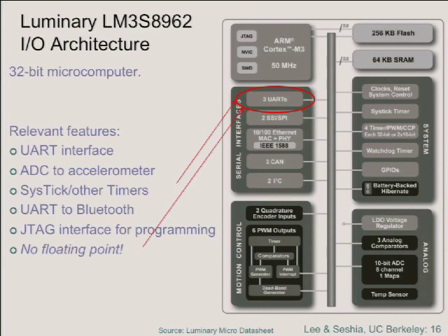By the way, the trends in interfaces are very strongly towards serial interfaces rather than parallel interfaces. It used to be that, for example, in the old IBM PCs, you had a serial interface and a parallel interface. A parallel interface was often used to connect to printers. A very common one was called a Centronics parallel interface. It has a whole bunch of wires, big connector. SCSI is another parallel interface that's used to connect to disk drives. These things are rapidly becoming obsolete.